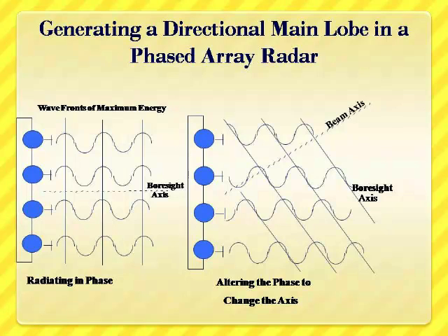So what we understood is that in an array, if the elements are given different phases, the response, that is the beam, is going to be pointing to different directions. Conversely, if you want the beam to be pointed at different directions, the input to the different elements must have different phase shifts. Now let us see how we can achieve these phase shifts to different elements.